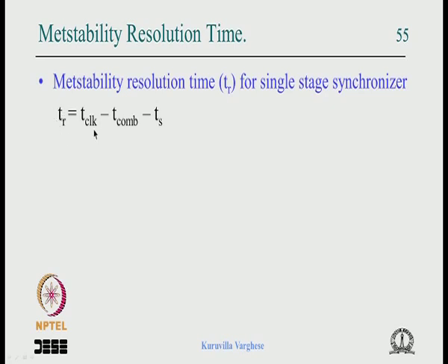Now one way of increasing it is to reduce the clock period, but that is not an option, because when you design a circuit we have a clock target, depending on the performance we need. Like we are doing some computation and we have a throughput requirement, so many operations per second, and we know the data path architecture, how many clock cycles it takes to compute the result.